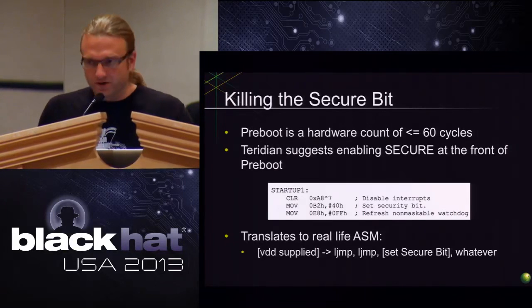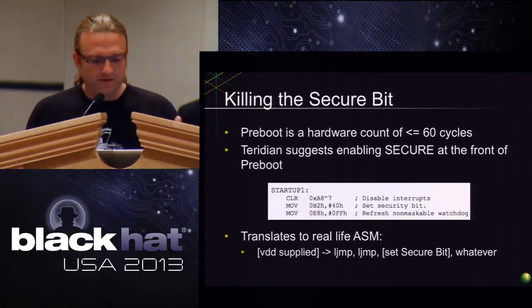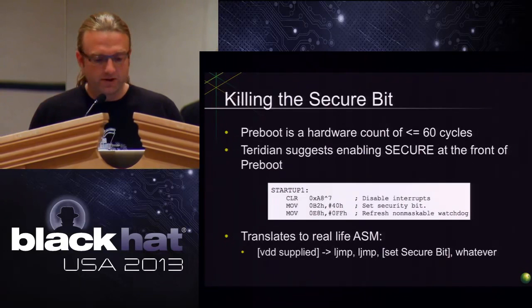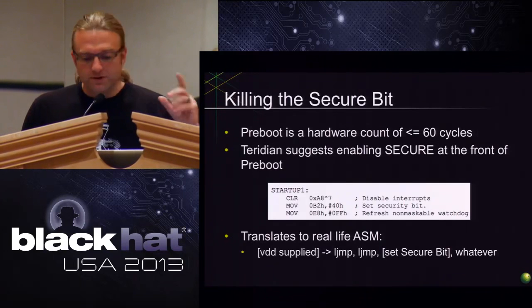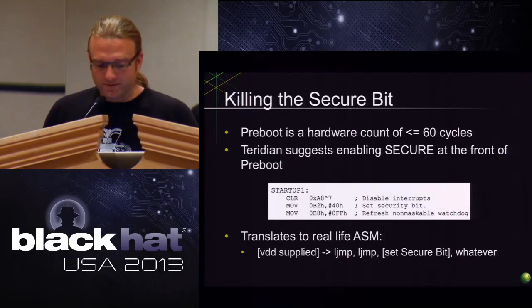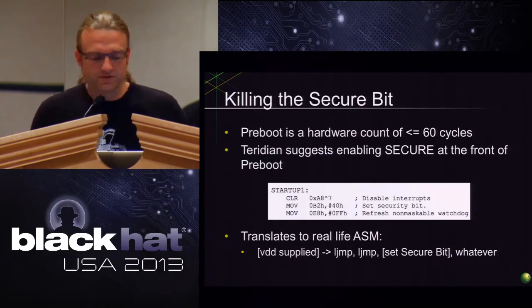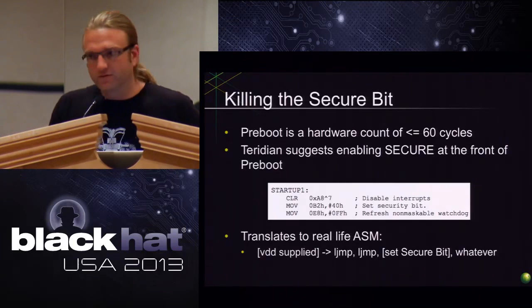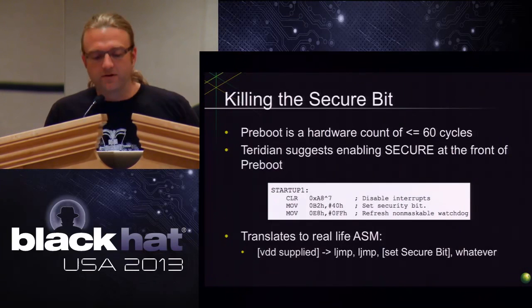When you start looking at all of the Teridian documentation, which is just massively fabulous, it covers everything in the world you would ever want to know as a developer. They give you the demo code to turn that on, and they tell you exactly where to put it. They say the very first thing you should do is, this is what your code looks like. If you do this, security will be set, and you can't debug the thing after it gets out of pre-boot. It'll never actually go into ICE.